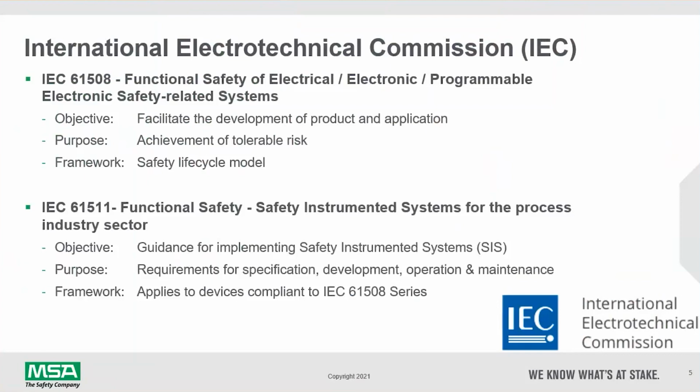The IEC 61511, which is for the process industry sector, takes those devices that are compliant to the IEC 61508 series and implements them and evaluates them from a safety instrumented system perspective.